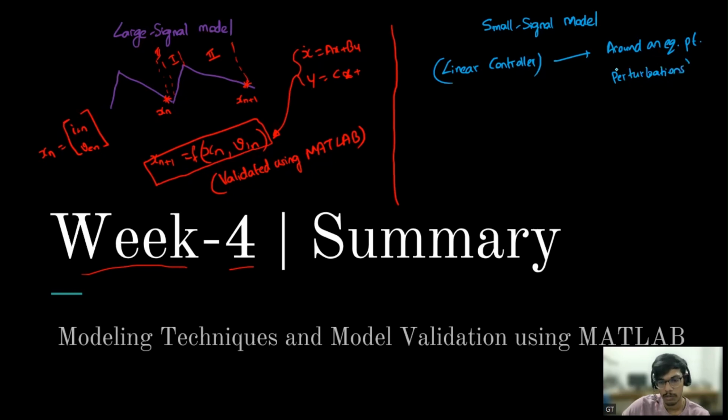You consider small perturbation. Our system is a non-linear system because of the switching, and we are designing a linear controller. So we have to linearize the non-linear system, and around that equilibrium point, we design the controller.